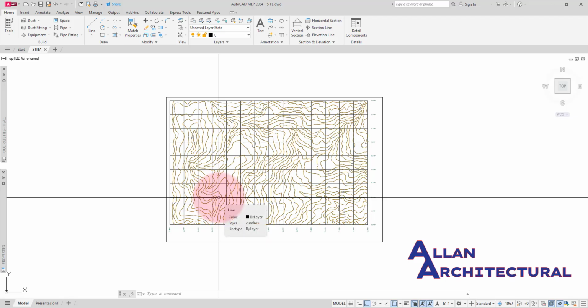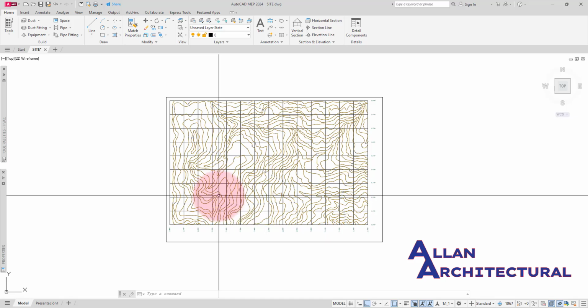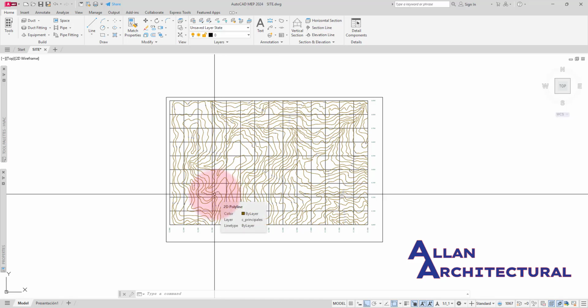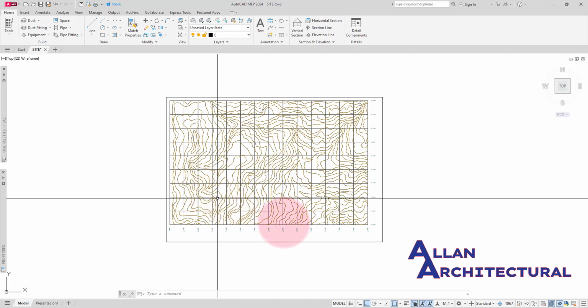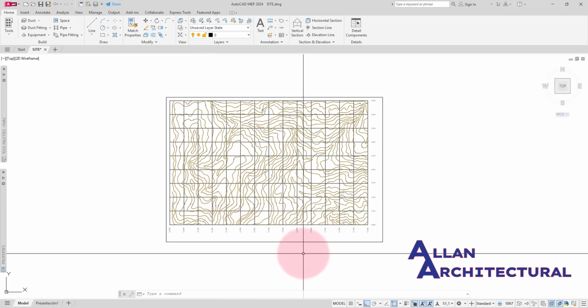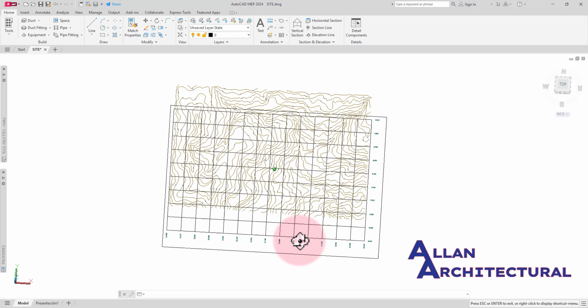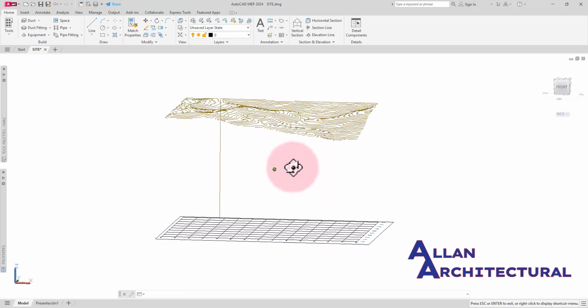All right, now there is an invisible coordinate which you guys do not see here, which is the z coordinate. All right, so we have a z coordinate which tends to act like the 3D view inside of the AutoCAD software. So I'm going to try and pan around a little bit where we can actually see this topo surface in the 3D view. All right, so I'm going to hold down my shift key and hold down the scroll button on my mouse, and then I'm going to zoom this out so you guys see what I'm talking about.